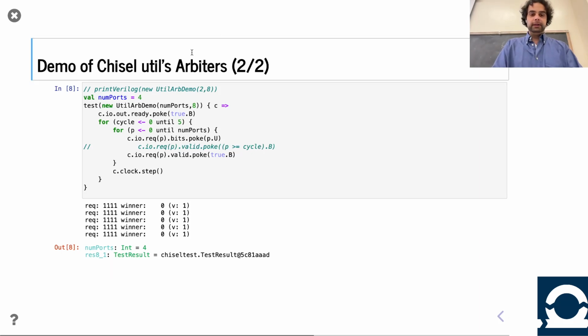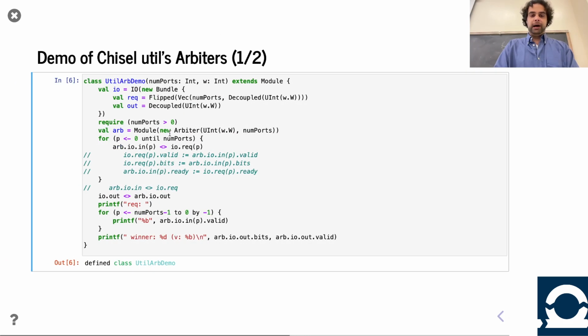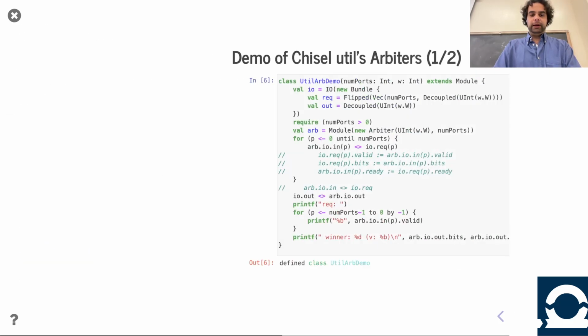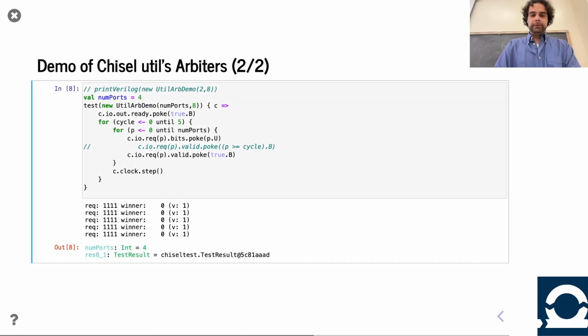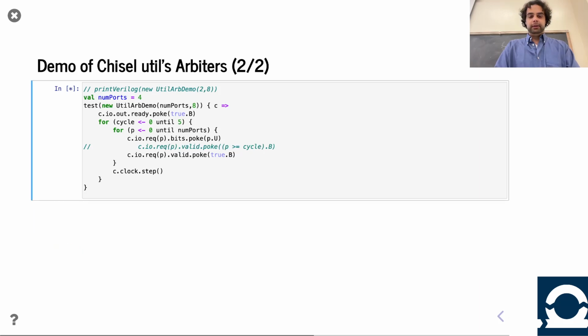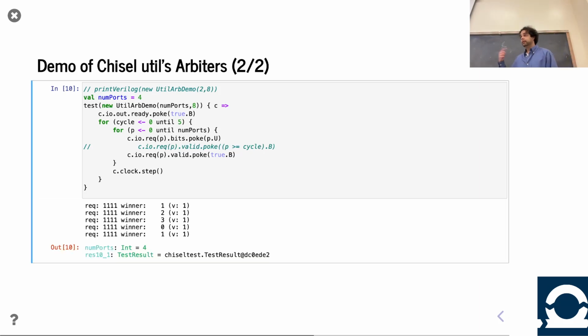So now to your point, let's start modding this. My memory is like a goldfish. So what is this? Round robin arbiter, RR arbiter. Okay, so now we're turning on the round robin. We had all zeros with priority based. With round robin, we see yes, it does change. But as you can see, it changes every cycle, right?